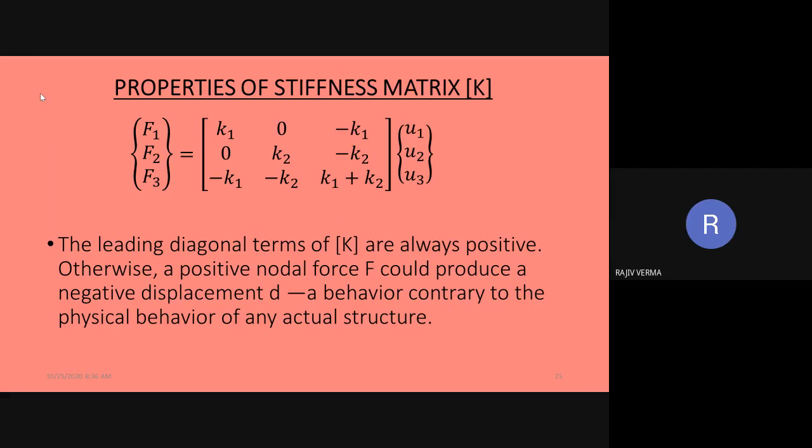And in fact, if you look at the discretization, you will notice that element number 1 and element number 2 happen to have a node 3 in common, which basically gives us a global stiffness matrix of the type which is on display. The row 3 and column 3 are going to have contributions from both the elements.